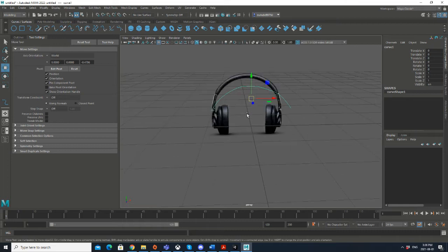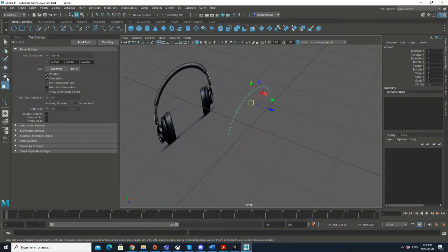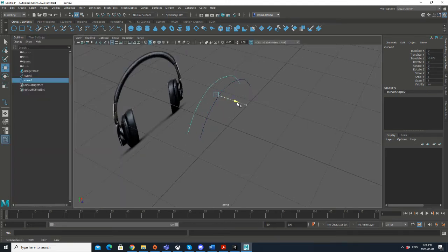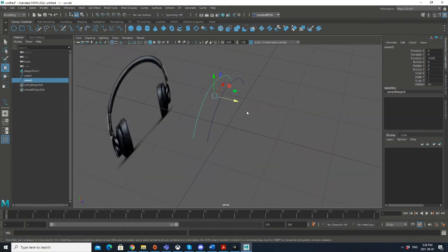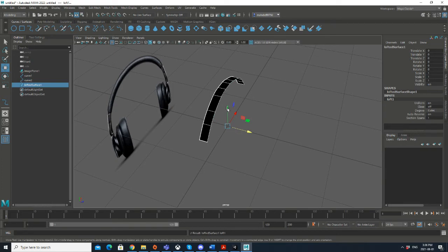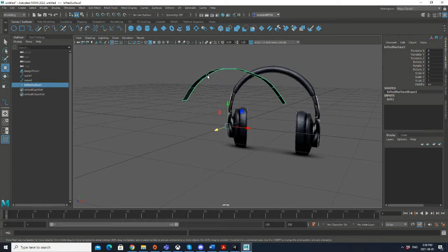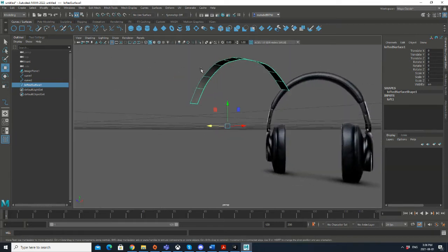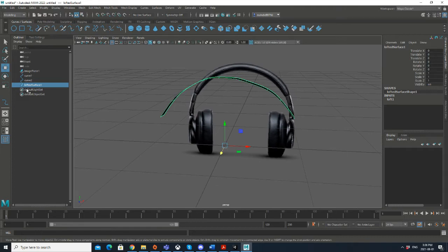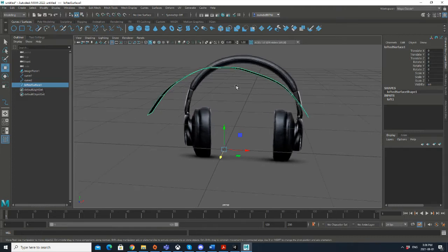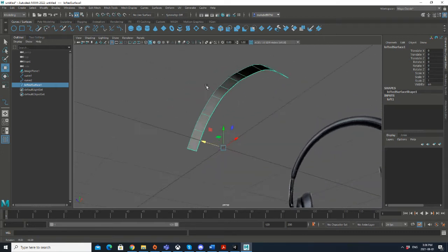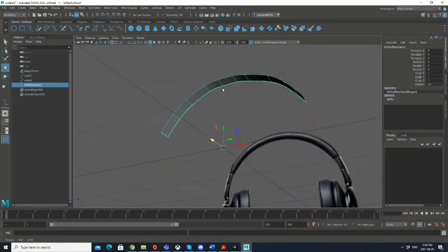if that's what you want. And I'm going to duplicate my curve here by Ctrl D and move it a little backward. And now what I'm going to do is to use the loft option here to put some faces in between them. One thing to note, it's not exactly the same as the faces we do. It is called a lofted surface for now, but that's good because we have a set of faces here.